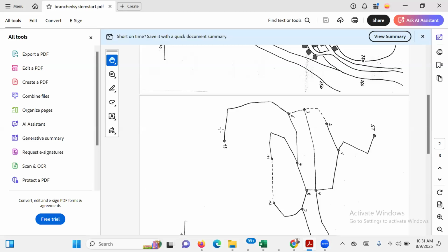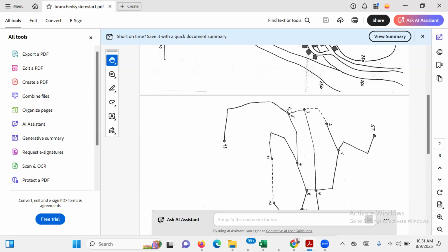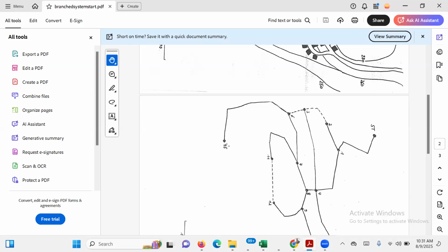But to size that pipe, you need to know the quantity. What quantity do you need at every node? Because the water is flowing from the storage tank to all the nodes. So if you use the wrong pipe, you only see that people up to the point of 3 or 4 have water. Those at 6 and 13 will not have water. Why? Because the diameter of the pipe is inadequate.